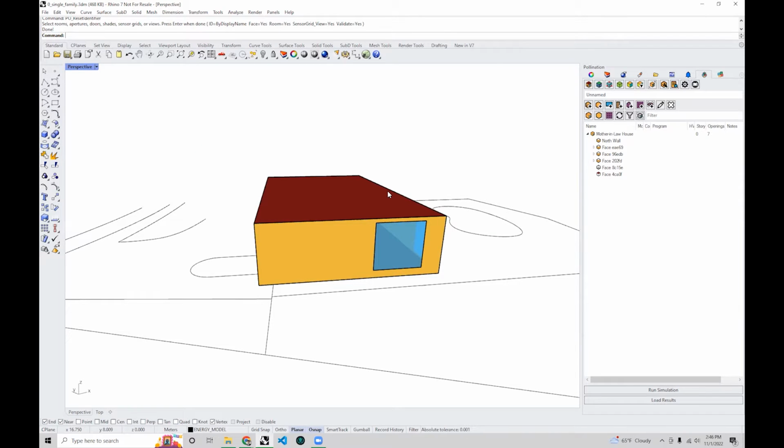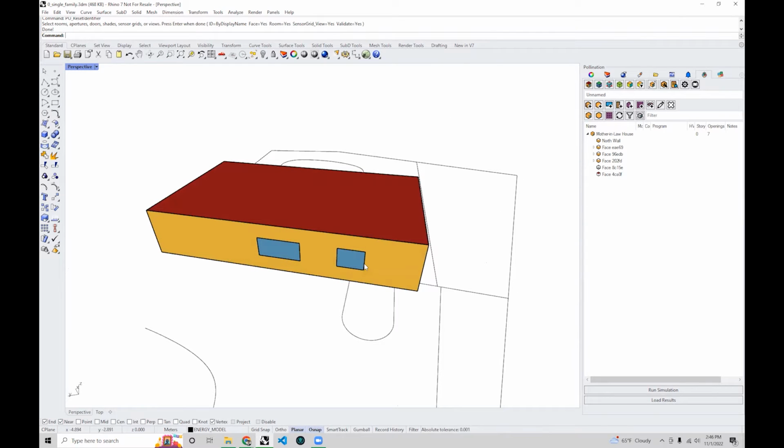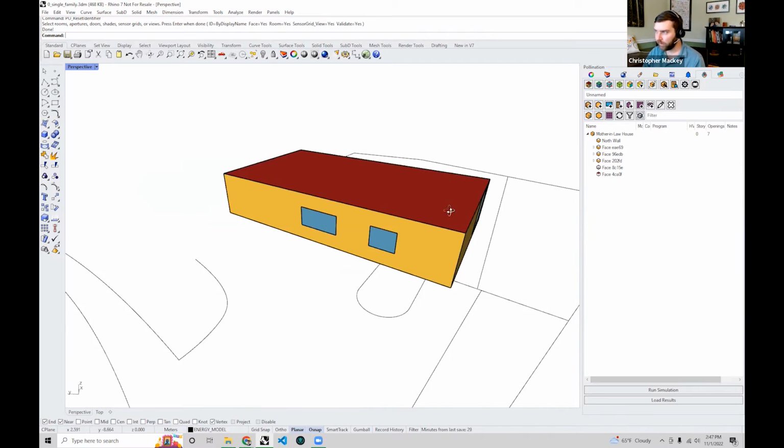We can have a better routine just to make sure, because for the Revit side we have a limitation: not everything is named. We have a name for the room, but then we can use that to name all the faces. That's definitely a very doable routine to rename. These days, that can be an app, or you can do it in Grasshopper, to be honest. I'll show you how to take the model in Grasshopper and reset all the IDs in there if you wanted. There are many ways to do this, but I hear what you're saying. Better defaults would save you from doing that.